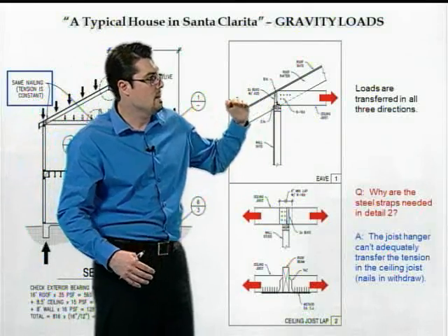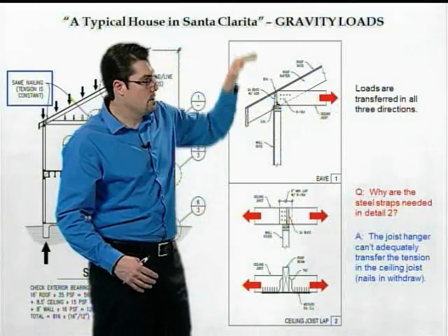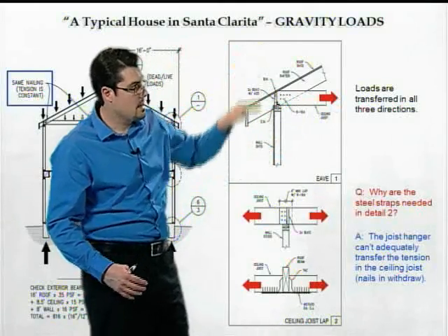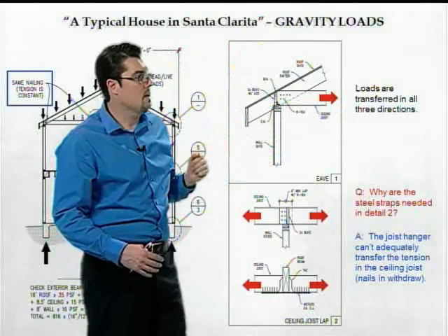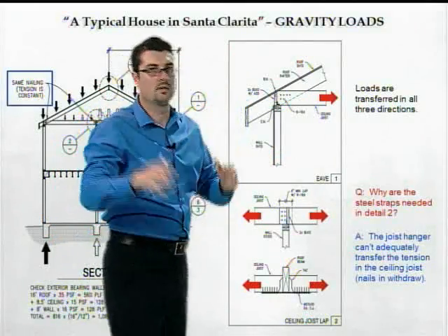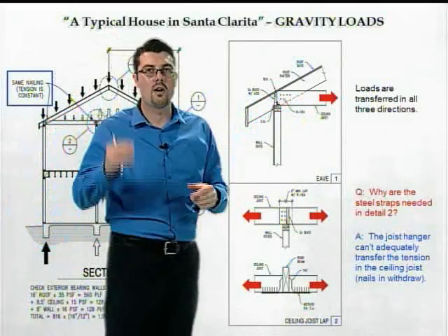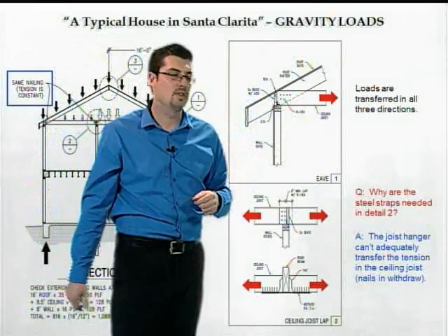You've got the ceiling joist force acting this way. You've got vertical dead loads, obviously, acting this way. And then you've got in-plane shear forces, acting in the plane of the presentation. All 3 of those forces are supported by all the different connections shown in the detail.